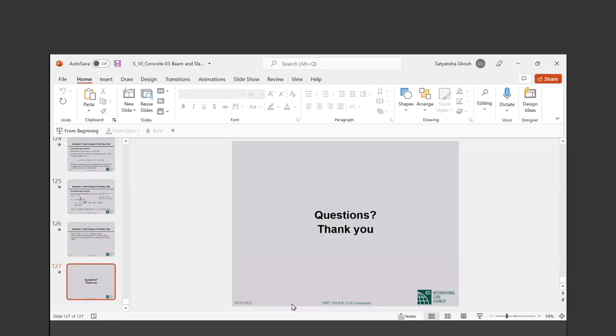But the horizontal shear reinforcement in a deep beam is mandatory. Yes. Yeah, Dr. Ghosh, you are right. It is 900 mm. And that is also mentioned in BNBC 9.5.3.2. So I'm just giving an extra information.